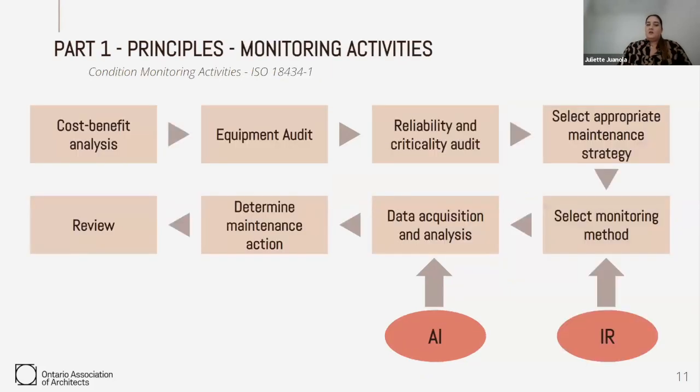These technologies can also be useful when it comes to monitoring activities. So let's say that an energy audit was performed on a building. It can be very interesting for a property manager to monitor the efficiency of its building envelope after the retrofit was performed. And one of the interesting monitoring methods that can be used is infrared thermography, because it is non-disruptive, because it is very straightforward, and also because it is very visual, so easy to understand.